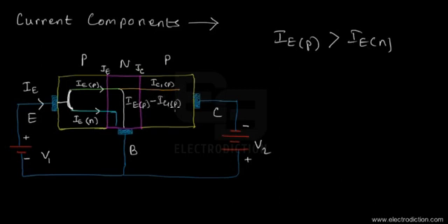Okay, so that is better. So that's the component of the recombination current that just enters into the base terminal as a part of the whole current that just comes from the emitter. And now if we again look at the collector base junction once again, then over here we can well see that